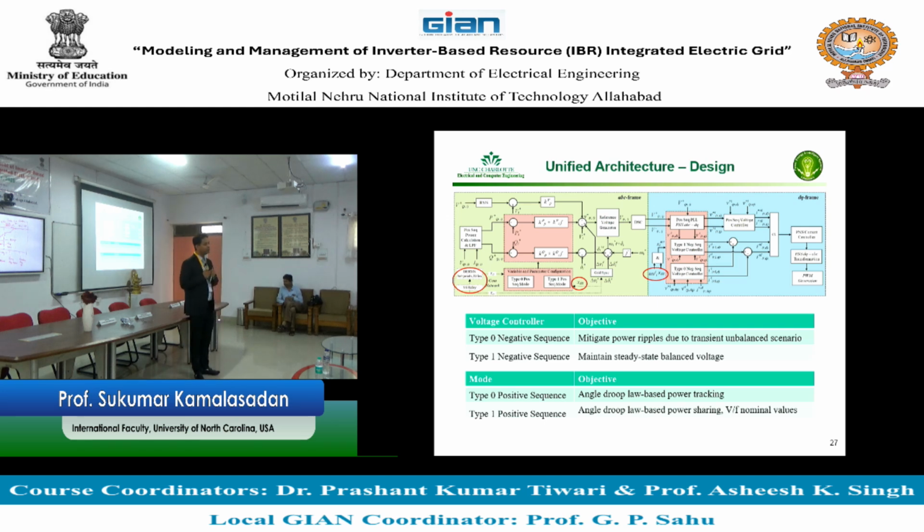This negative sequence component, when you extract it, even in normal operation, is good. Suppose you have a normal operating condition, you have harmonic content sitting there. This ripple and the harmonic content can generally be represented in the form of a negative sequence. So if you push negative sequence current, you can actually take care of the harmonic content as well. To some level, you obviously still need filters to take care of the harmonics, but you can actually improve the harmonics as well.